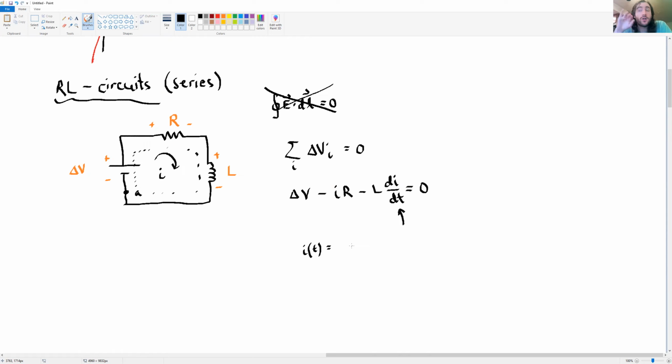As the current increases, there is a magnetic field created in the solenoid there, the inductor, and that changes the flux through that coil of wire, and that induces a voltage which opposes that change in current, the increasing current. And so I think you can already see that my choice of the polarity of the voltage there is correct for the inductor. It has to oppose the increasing current. So it wants to drive current in the opposite direction.